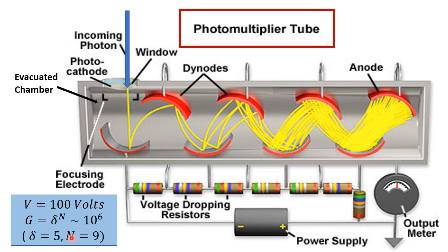So imagine that this was about 9. You would quickly build this up to about a million, a factor of a million, right? So this is the kind of great gain and multiplication of the electrons which the photomultiplier tube is known for, and hence is an extremely sensitive device.